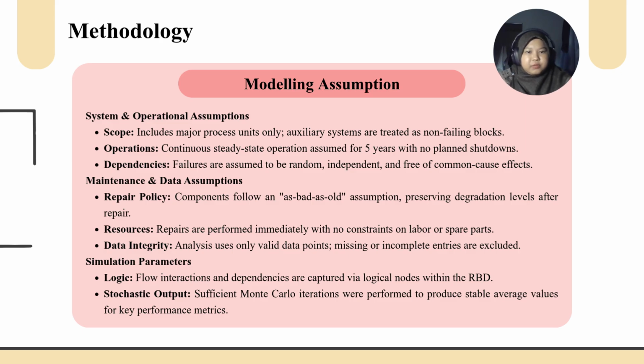Moving on to the next slide, which is modeling assumptions. To ensure our simulation was both mathematically sound and focused on the most impactful data, we established several key modeling assumptions. First, regarding system scope, our model focuses strictly on major process units. Auxiliary systems were treated as non-failing blocks to prevent minor peripheral issues from skewing the high-level plant availability results.